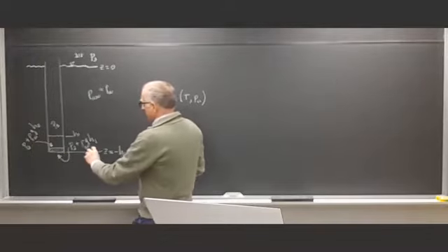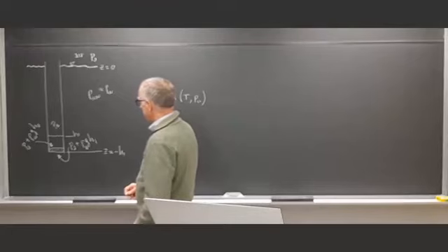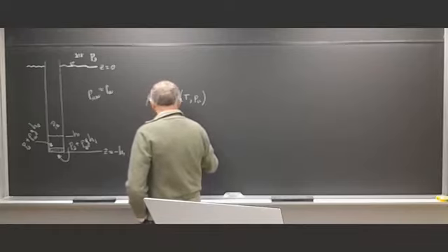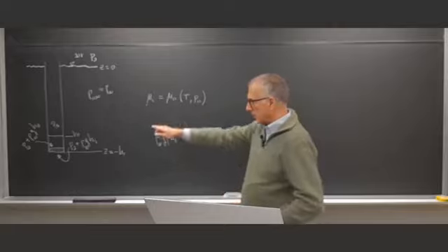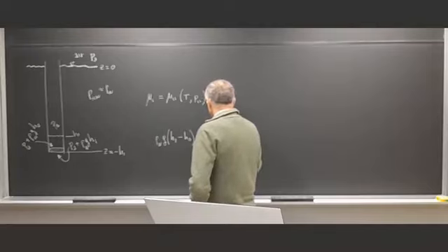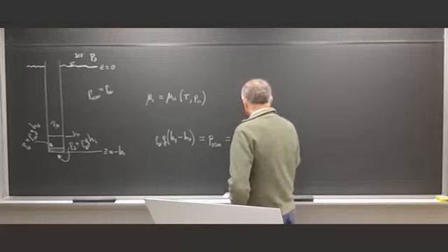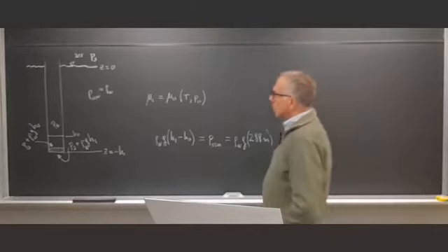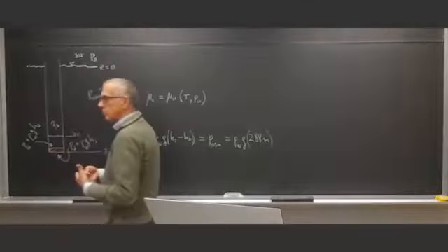Okay. So across the membrane, I have a pressure difference. Okay, so the pressure difference is rho W G times H1 minus H0. And if I am at equilibrium, at the temperature that prevails there, that is equal to the osmotic pressure. So that would be the equivalent of rho W G times 288 meters. Okay. So there is a huge difference in pressure there. So this porous plug must be able to sustain that pressure.